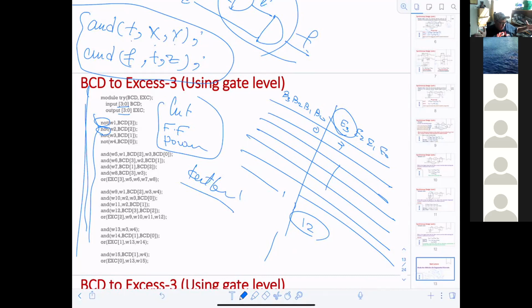If I add 3 to 9, whether it's going to give me 12 or not. If any 10 will happen, if I push 10, what will the output be? It shouldn't be anything, right? If I push 11, do you think 11 exists in the BCD? No. Stuff like that, those are corner cases.